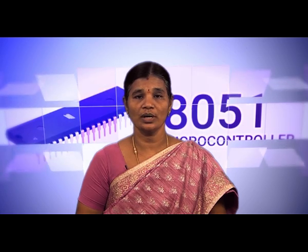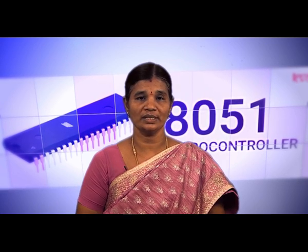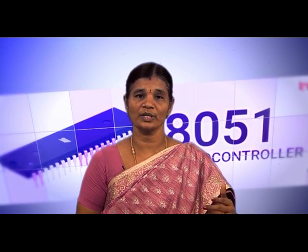In today's session we have discussed what a DAC is, that is a digital to analog converter, defined by the 0808 IC. That IC is made up of the R to 2R ladder method, the conversion technique, and only then can we identify the resolution of the conversion. Here we have discussed the 8 bit DAC. In this, the digital signal is given from the microcontroller, then the 0808 IC will convert it and give the analog output, which is a very small value, that is why we are additionally adding the operational amplifier. It will give the amplified signals.